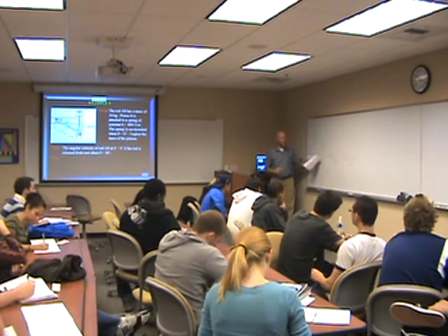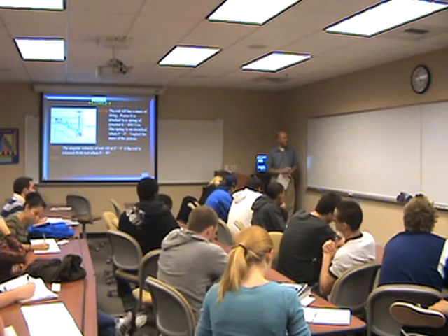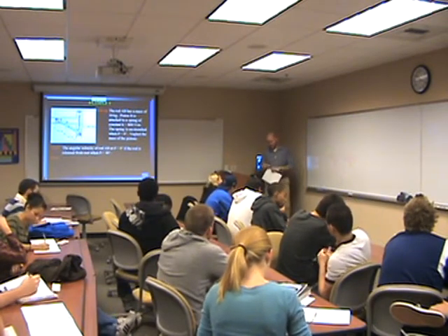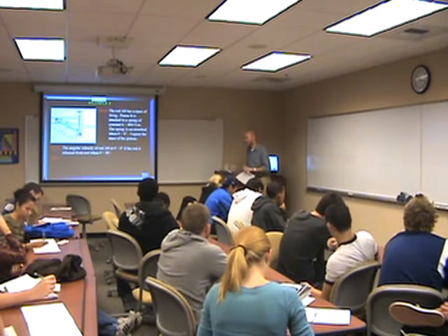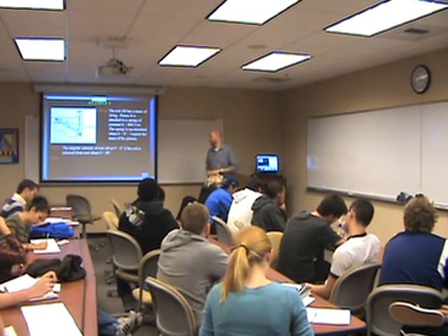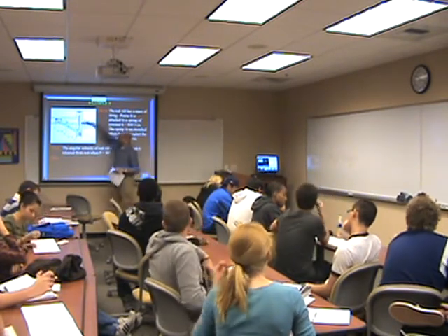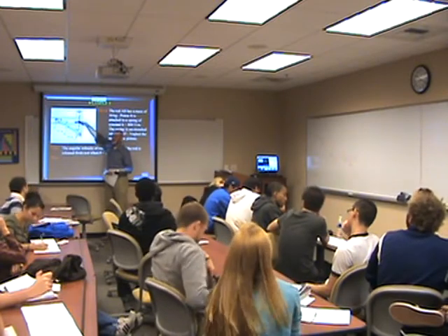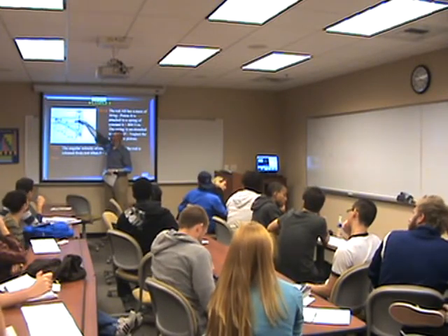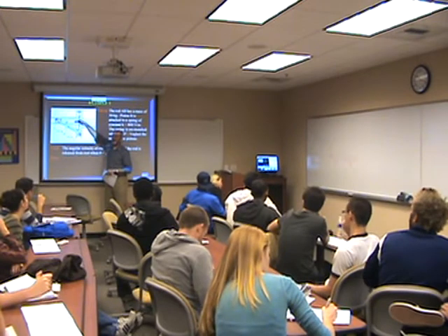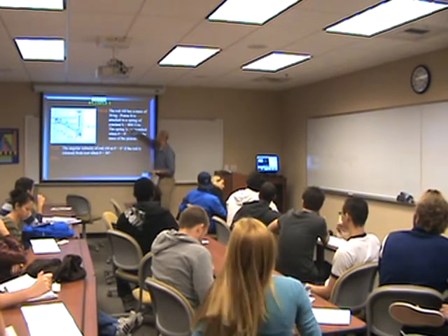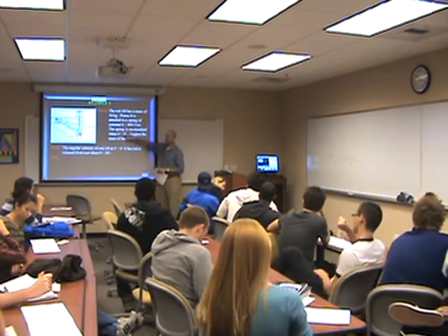So our final kinetic energy is equal to, well, what's our initial potential energy? Where do we want to set our datum? Anywhere. If we set our datum when theta is equal to 0, that's our height equal to 0. Our spring is unstretched when theta is equal to 0, so that's a good datum.